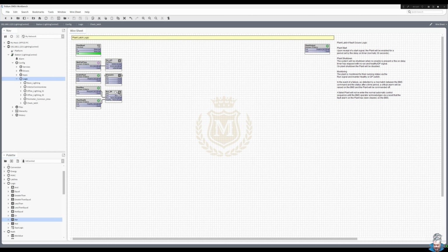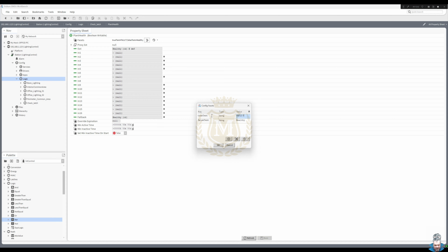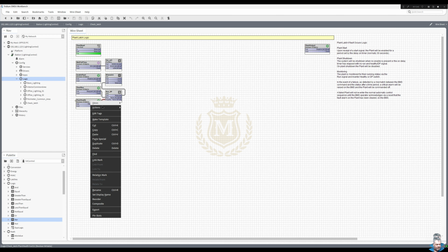So we take that and put that into the DP, because we've proven DP, we've got to be healthy, so that's got to be true. So I presume what I could do, oh yeah, that's got to be true. No, sorry, it's got to be false. So I could do with being that the opposite way round. So it's fail safe. Anyone cuts the cables or whatever, it will go into fault to the IO, to the input. So we'll have that fail safe.